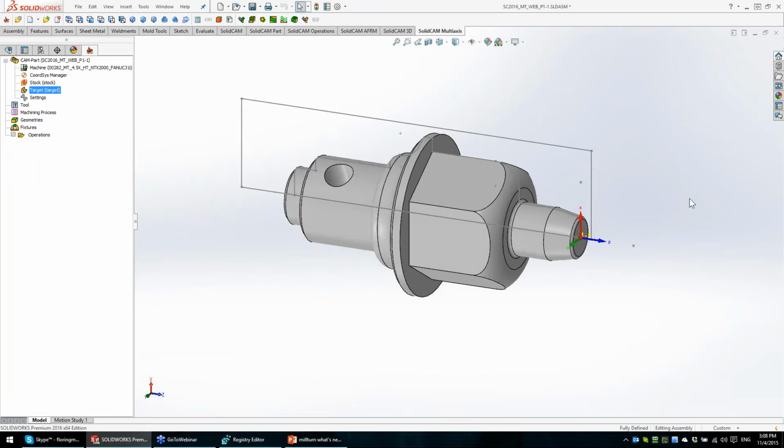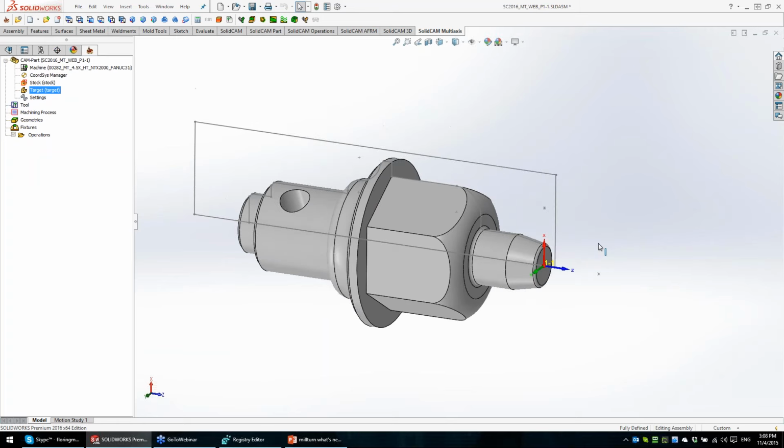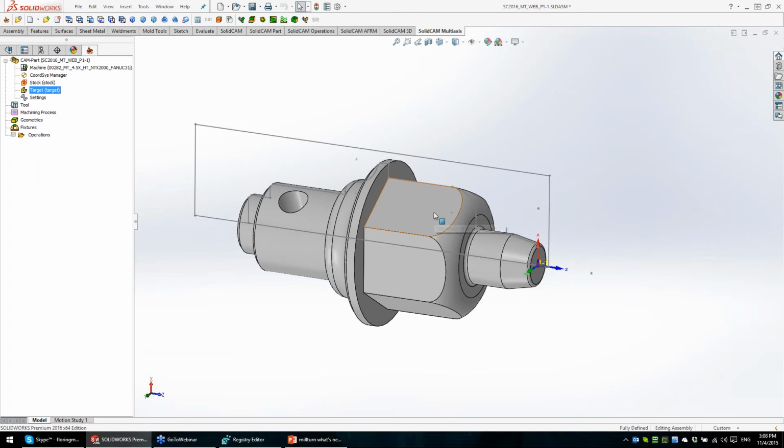Now, as I started to tell you, working on upper turret, main spindle, with coordinate system Mach 1, position 1, when I define a geometry, if I want to change this operation and move the operation from upper turret to lower turret, it means it's going to a different submachine, a different coordinate system, a different Mach.